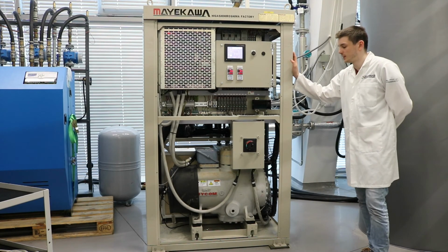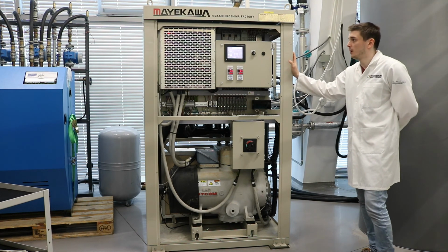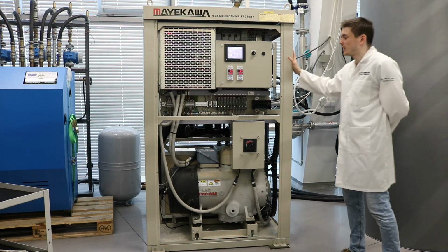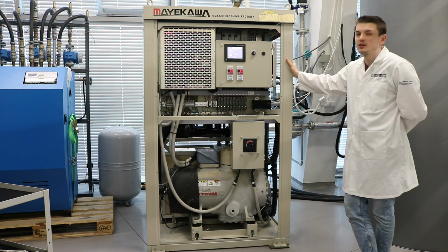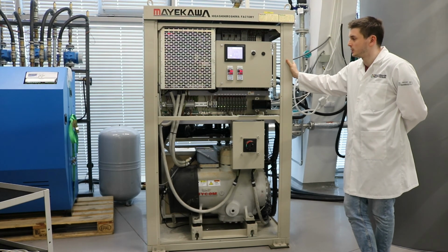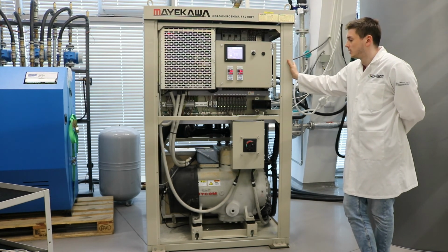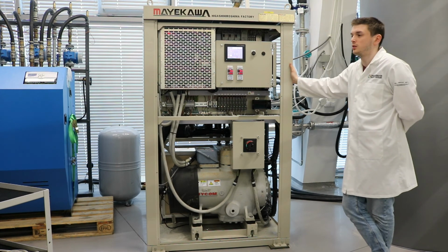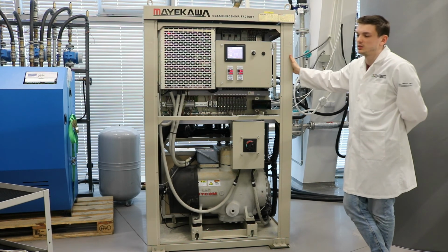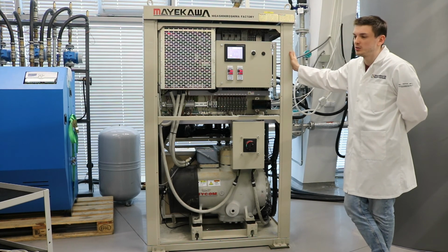Here we've got a very big heat pump that is different from the commonly used ones because this is a high temperature source heat pump. Why high temperature? Because it can deliver up to 90 degrees Celsius. So it can be used for a domestic hot water system or for building heating, which has radiators instead of floor heating and needs a higher temperature source.